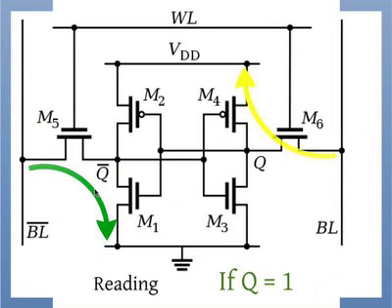If Q is 1 and you want to read the memory, you apply logic 1 to the word line WL, and you read out the difference between bit lines. Okay? I showed only one here, but typically there's 2 coming up, and we look at the difference between these. So you query this, and you apply a high here, you read this out. You see a 1. This bit line will get pulled up to VDD, this bit line will pull down to ground. Okay, the opposite will happen for the other situations.